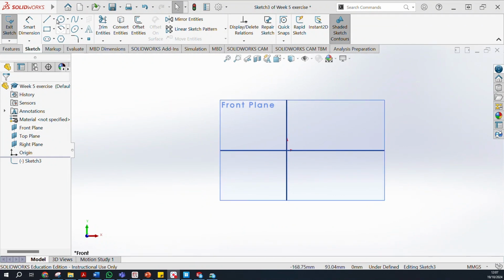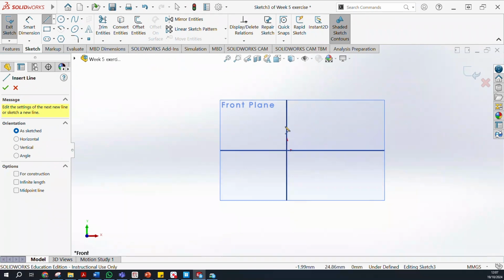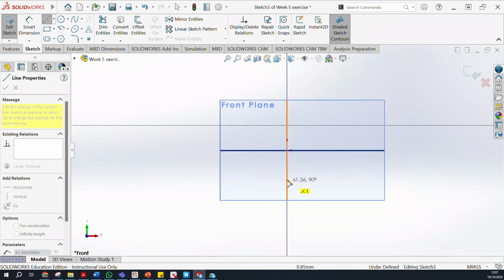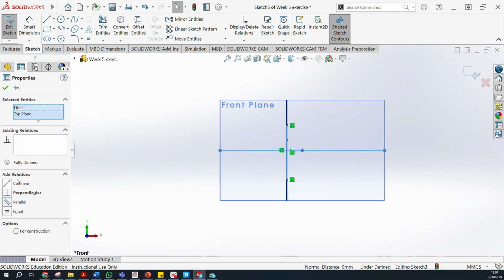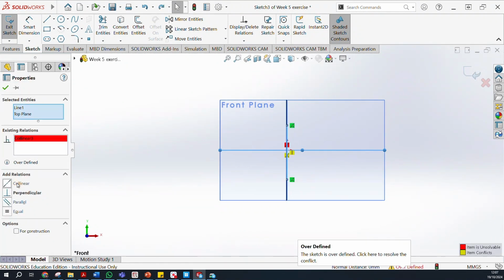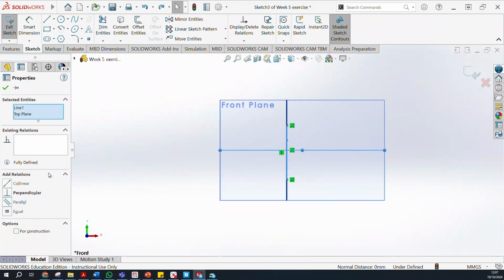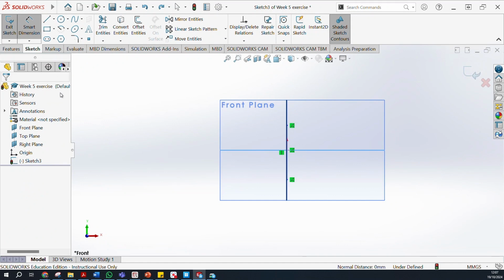To draw a ball, we first need to make a D shape, so that we can revolve it to make a complete ball, like that. And I want to make this one symmetrical along the x-axis. Let me do it with simple dimensions.